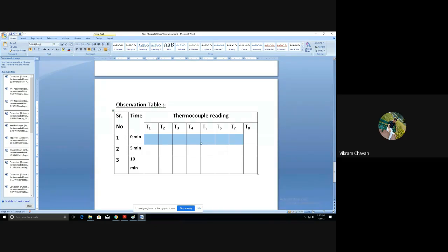So in that case, you require these temperatures, and then you have to calculate the surface temperature. After calculation of the surface temperature, you have to calculate the mean film temperature, because the properties of air we have to consider at a mean film temperature. Mean film temperature is nothing but the average temperature of the surface and the ambient air, or the surrounding fluid to that particular body. The reciprocal of the mean film temperature in Kelvin will provide you the coefficient of volumetric expansion, that is beta.